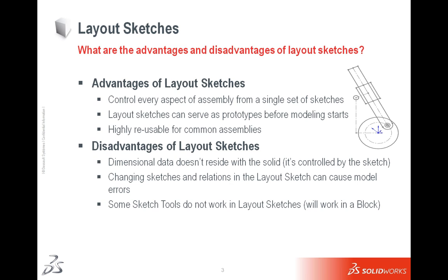Layout sketches can also serve as prototypes before the modeling starts. We can reuse some or all of that information to create the parts and assemblies. They're highly reusable. If I want to take a layout sketch and save that information and reuse it somewhere else along the line, I can absolutely do that.